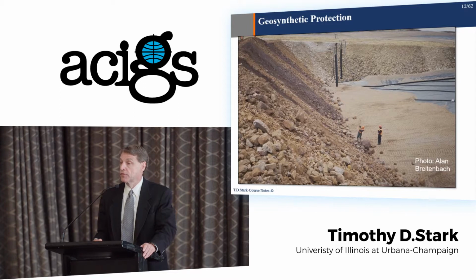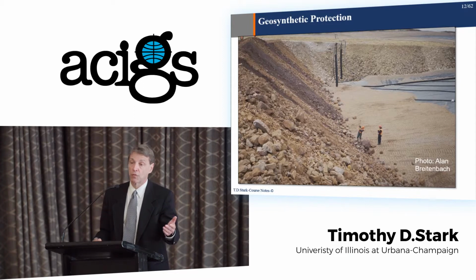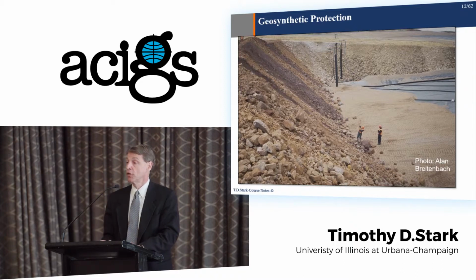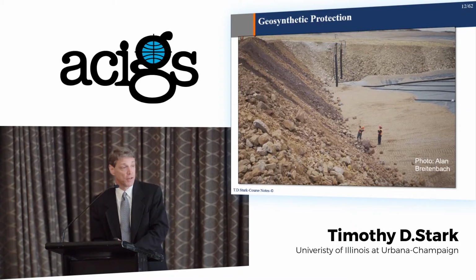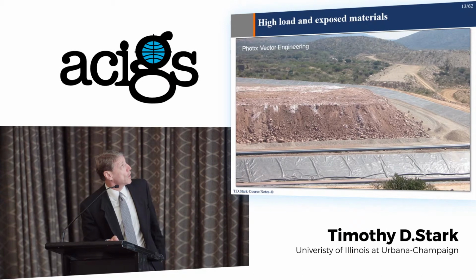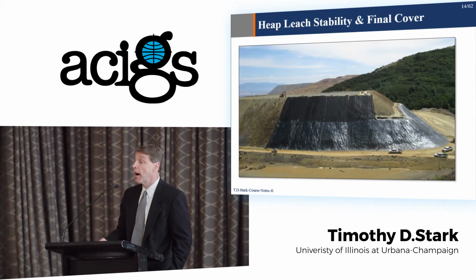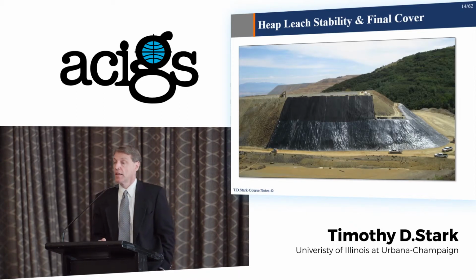You can have different puncture resistance from the geomembranes. A reinforced geomembrane has a good puncture resistance. Rob's going to talk a little bit later about bituminous geomembranes, and those also have a very good puncture resistance if that's the key design function you're looking for. Okay, so here's the whole operation. There's the little containment berm around the side, the geomembrane going into an anchor trench, and the pile coming up on top of it. So that's sort of the bottom liner associated with heap leach.